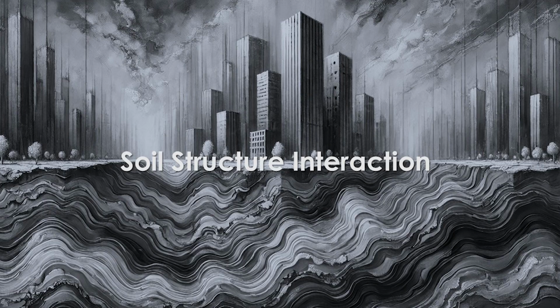well managed. I know in your model, in your project also, when you model a frame or anything, normally you draw a short line and then you put the hash and you say fixed or pin. And then you forget there's a whole thing below the building. And then we just ignore it and we just say, oh, my structure ends here. I don't know what happens after that. And then you calculate the load and then you apply it to the foundation and then you remove the structure as if the structure doesn't exist and you design the foundation. And that's just not how it is.